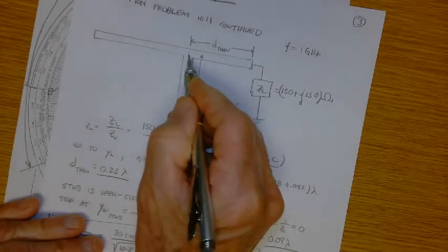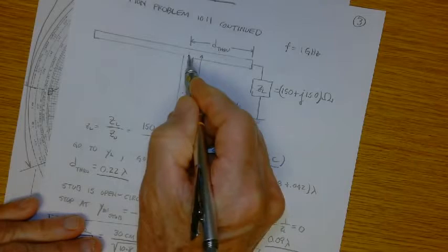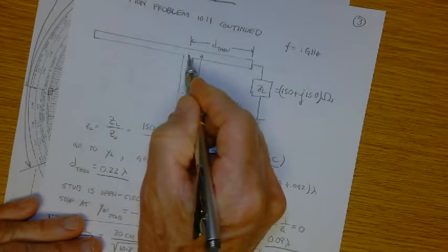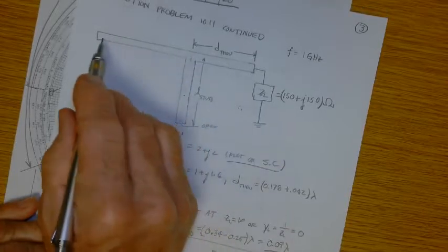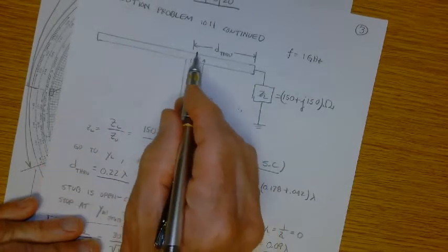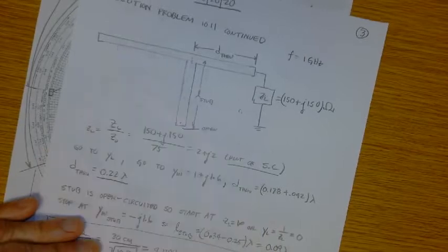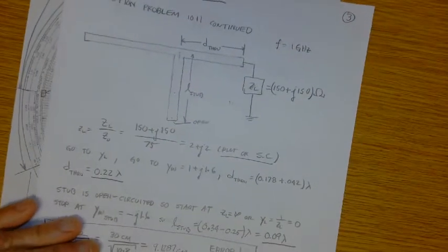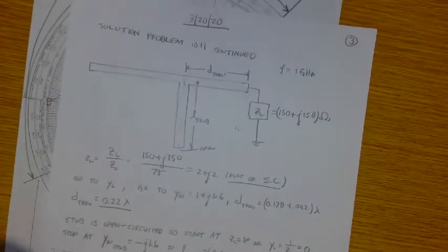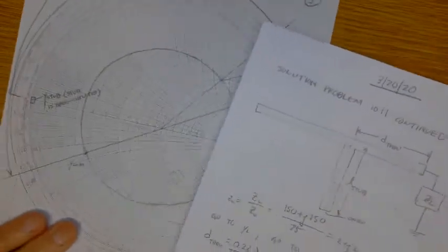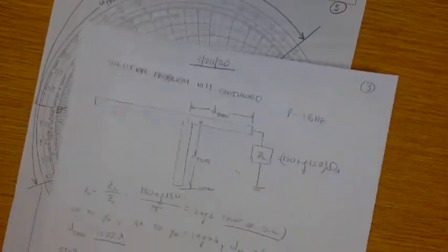So little z at that point is 1 over 1, which is still 1. And so honest to goodness, big Z in there is 1 times Z naught, or 1 times 75, which is 75. So as far as this line's concerned, it sees 75 ohms and there's no reflections. That's the whole intent here, right? Remind yourself of what you're doing, why you're doing what you're doing.